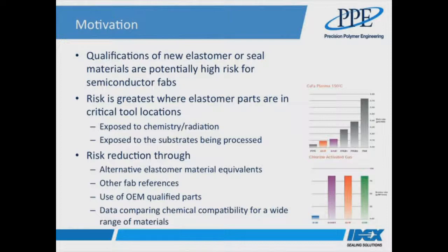Now then, equipment providers have a lot of inbuilt monitoring of the critical process parameters and also various parameter feedbacks to monitor the tool. And all this data is logged in real time to ensure the equipment is functioning correctly. Good examples of this would be gas flows, pressures, powers, and various plasma feedback parameters. Again, all good stuff. However, during processing, all parts of the chamber internals are exposed to whatever chemistry is going on, and that obviously includes any seals or O-rings.